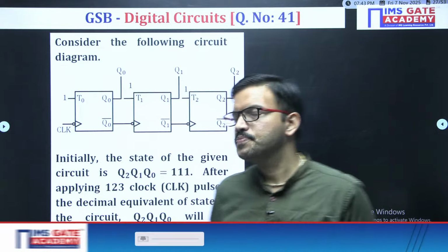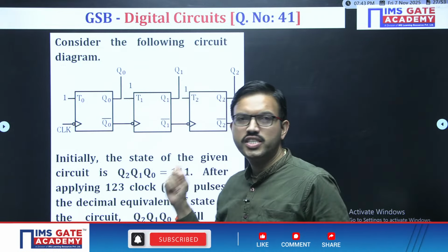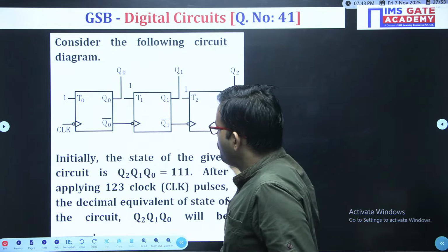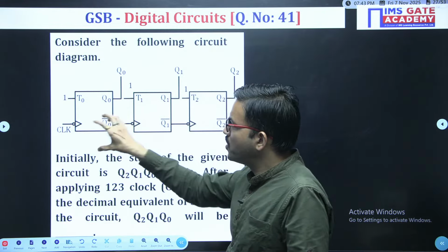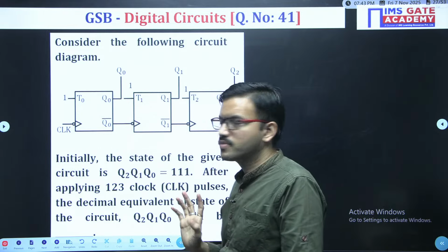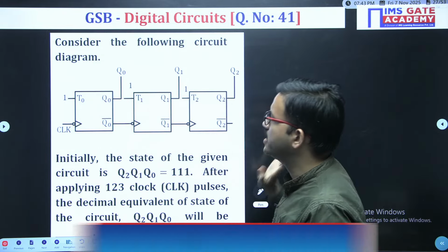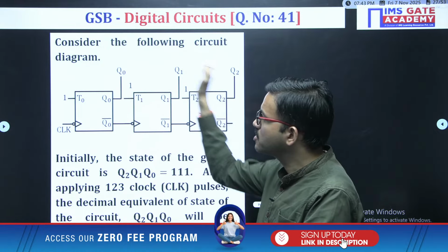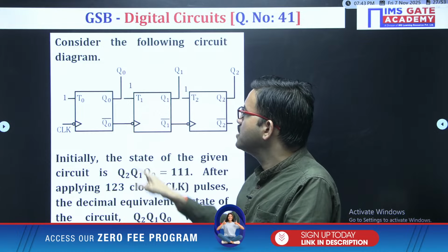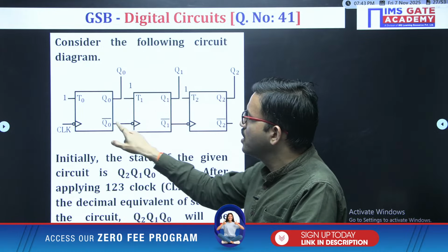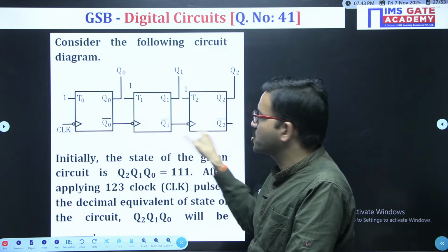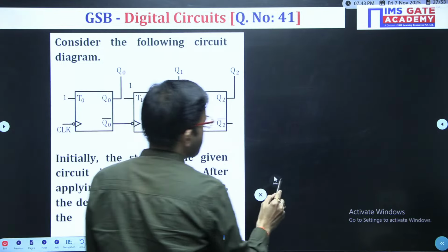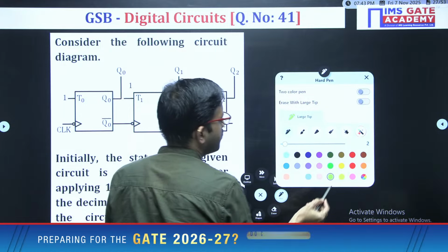There is no doubt in it. But whether it is an up counter or down counter, that we have to decide. Very simple. For every flip-flop, the corresponding edges are negative regarding the clock signals you are having. And if you have connected the normal output, then that circuit will become an up counter. But in this case, instead of normal outputs, the configuration is the complement version. Just for easy understanding, I'm writing.